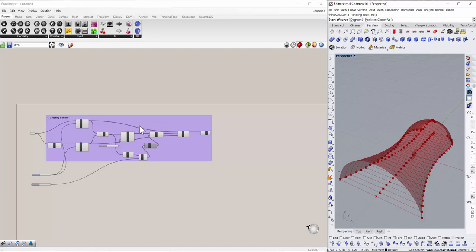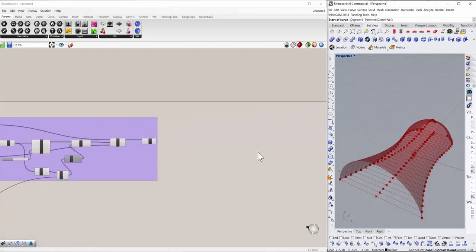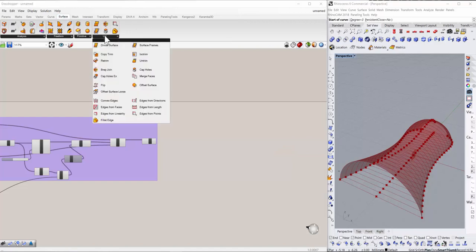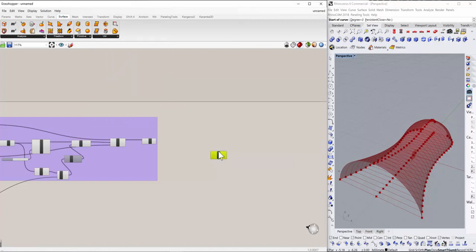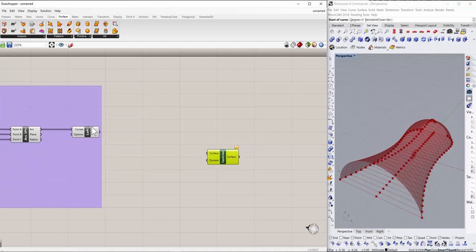So how I would start the paneling is I will use a subsurface function that is basically isotrim. Here you can go in the utilities and find this option isotrim and put all the surfaces in here, and now divide domain.